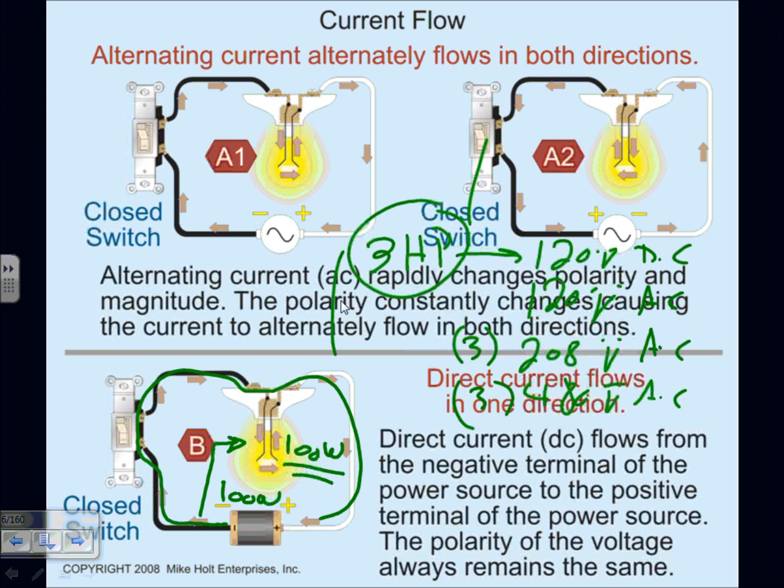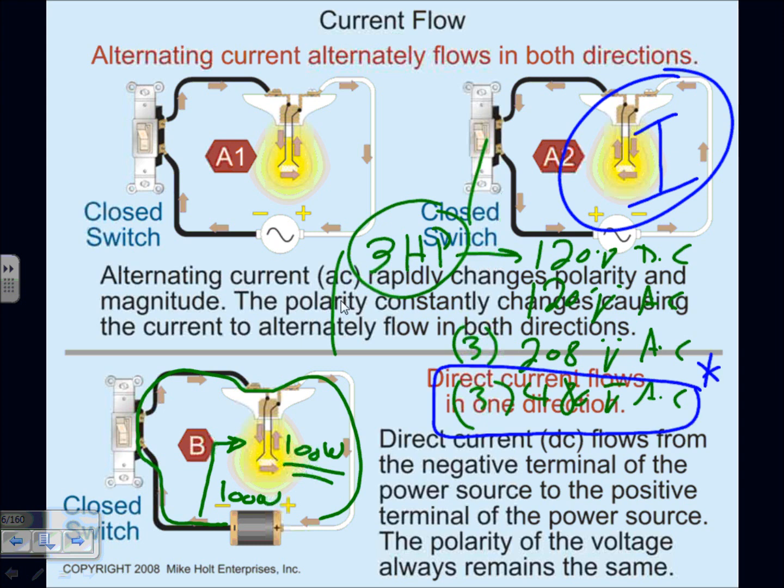The voltage changes. So what changes when you change the voltage? Anyone can tell me? Big I changes. What's I? The current. The higher the voltage for the same amount of power, the lower the current. So at which point do you expect the current to be the lowest? Right here, the highest voltage will give you the lowest current. Who cares? Lowest current means smaller conductor, more efficient. Smaller conduit, more efficient. Less voltage drop, more efficient. Can you guys see? It's coming down to efficiency.